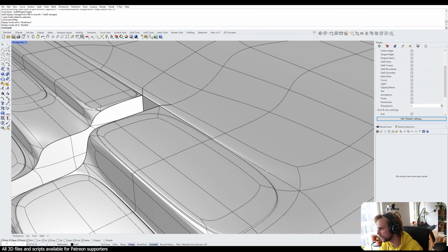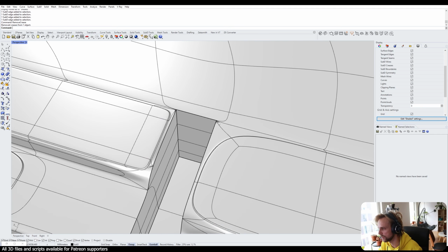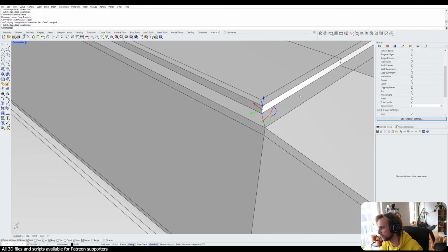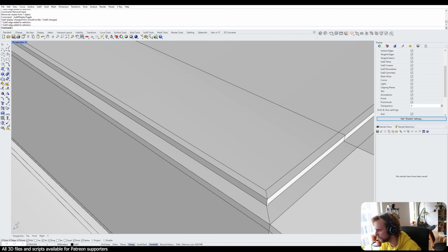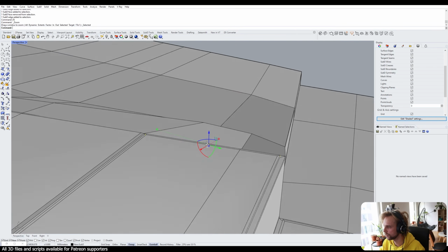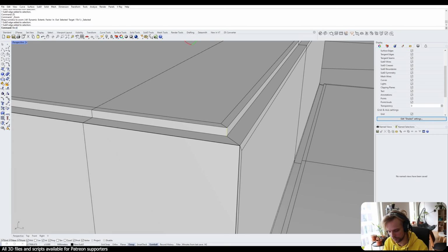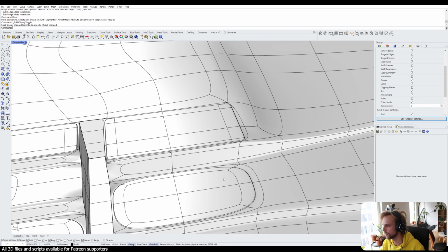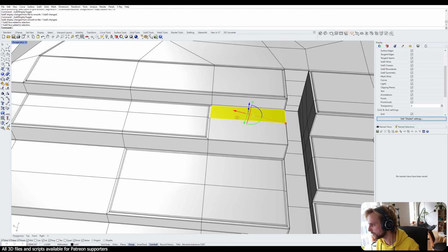And also I really hate the crease here, like these creases here, so I'll just remove them. Better to just have a shading issue there than to have it everywhere, right? So let's select that, ZS to zoom selected so that it's easier to navigate with the camera, and then bevel. I used 50, right? Something like that, 50. And we have another island. So you can play around with the islands as you wish.